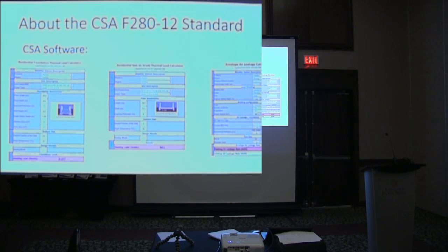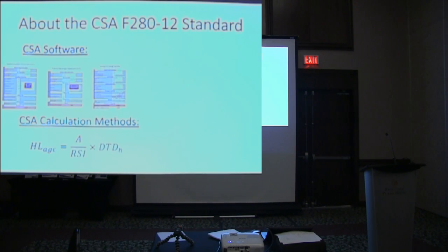Same with the air leakage. So basically we want to determine how much natural air change is our building going to have. So you put all of your inputs into here again, and out come your natural leakage rate in air changes per hour. So for heating, for this example, we got 0.1 air changes per hour of natural ventilation. Sorry, natural infiltration.